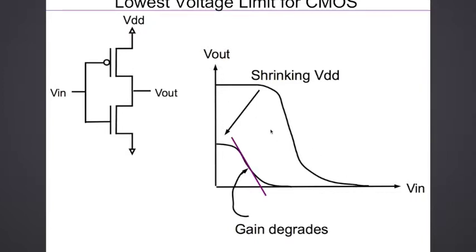A 45-degree line is a slope of -1. So everything is kind of okay. Whatever input you give, you get an output which is not too far off, right? Whereas here, there is this band where, when the input is less than this particular value, the output voltage is much higher. So it really separates the levels.